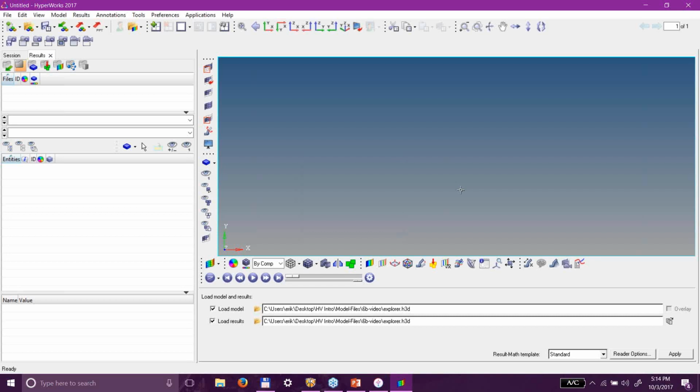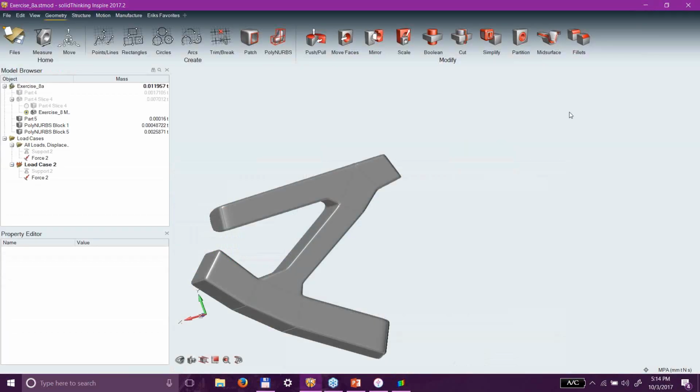It's used to export deformed shapes. So if I've deformed a body and I want a mesh of that deformed body, I can do that. But it also works great with optimization. So I can export the shape. It'll be an FEM file. I can bring that directly into Inspire, and then have some fun wrapping NURBs around it.